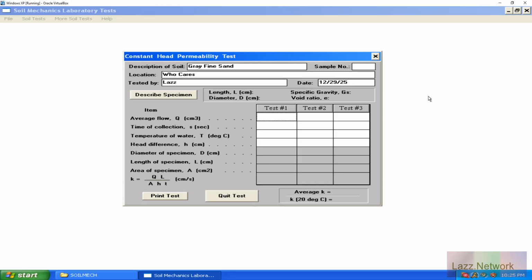if there is a density requirement for the material to be utilized, let's say they want 95% compaction. So obviously you have to have a proctor to go with that. And whatever you get for that proctor value is what's going to help determine how much you need to compact it.